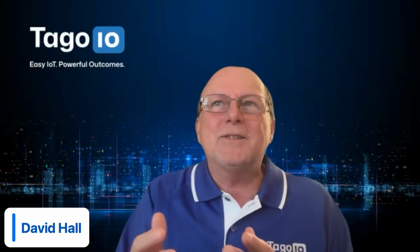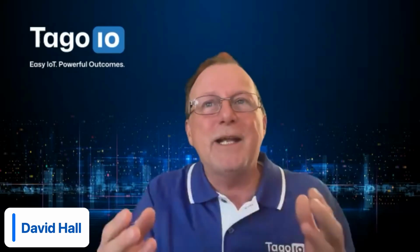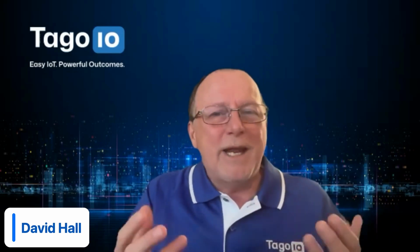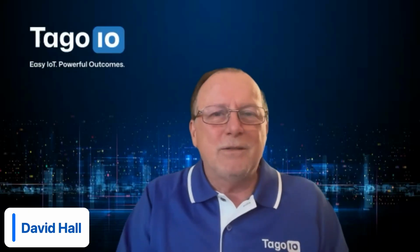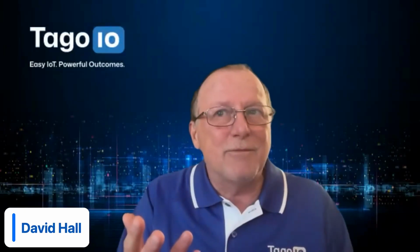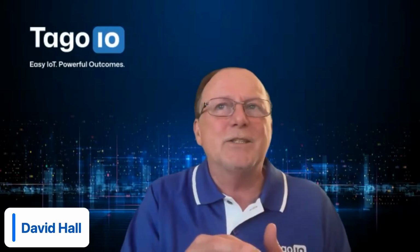That's a great segue, because if we talk about best practices for reliable data collection and transmission, what are some of those best practices? You need reliable data, and you need to be able to collect it and transmit it. Define data frequency intentionally. Focus on actionable intervals. Monitor device health, not just the sensor values: battery level, signal strength, last communication time, for instance. All those are considerations when you're talking about data collection and transmission.